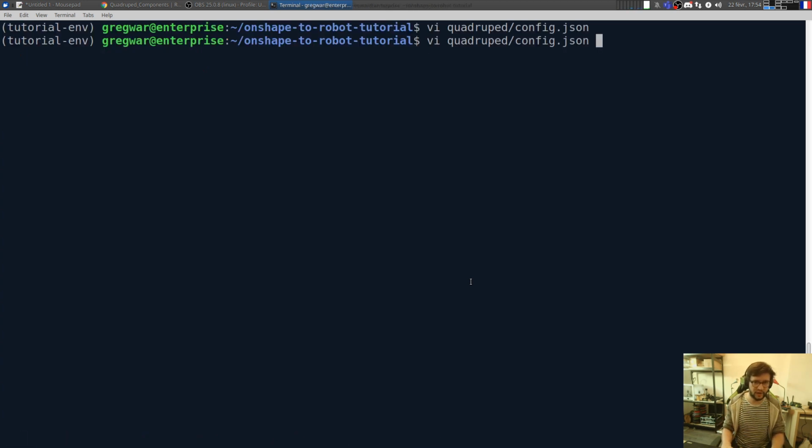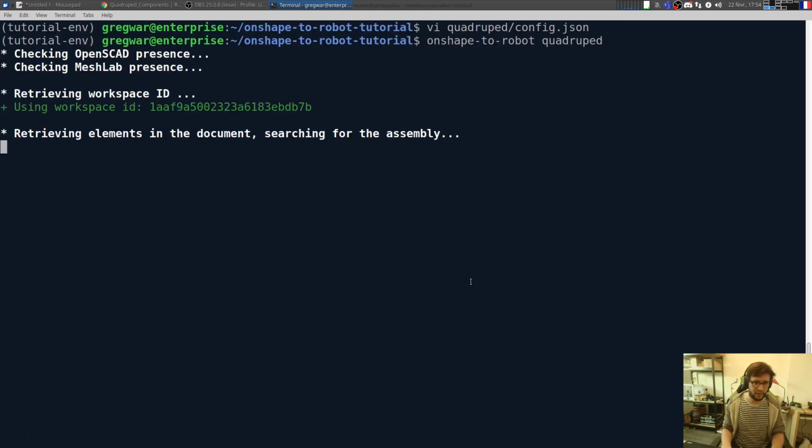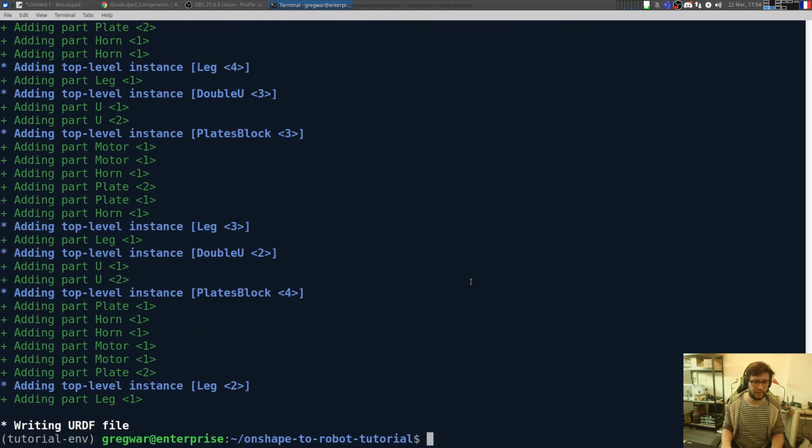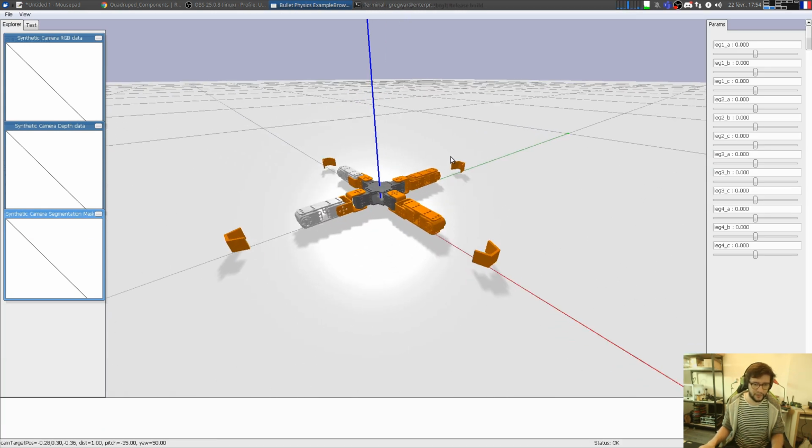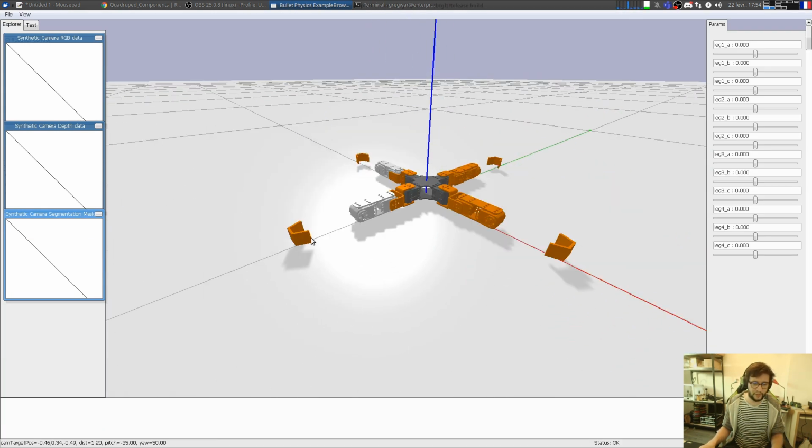So if I use this flag to true and start the import again, and then load it in PyBullet, you can see this time that even the visual now are the same as collision. So I can't see my full legs anymore, because those 3 cubes are also in the visual section. And this is getting the robots loaded way much faster. And if you don't need a very fancy visualization of your robots, I strongly recommend that you pass this flag to true. Of course, this only has positive effects if you did the proper pure shape approximation on your raw robot.